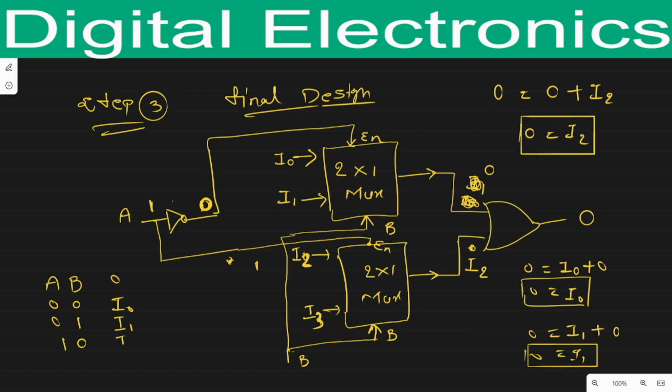O equals I2. Okay, and the last case, when both inputs are 1 1, similarly the upper one will be deactivated and the lower will be activated. B equals 1, so this I3 will be transmitted from the lower path through here. So here we will get I3. So what we will get? We will get O equals 0 plus I3. It means that O equals I3.